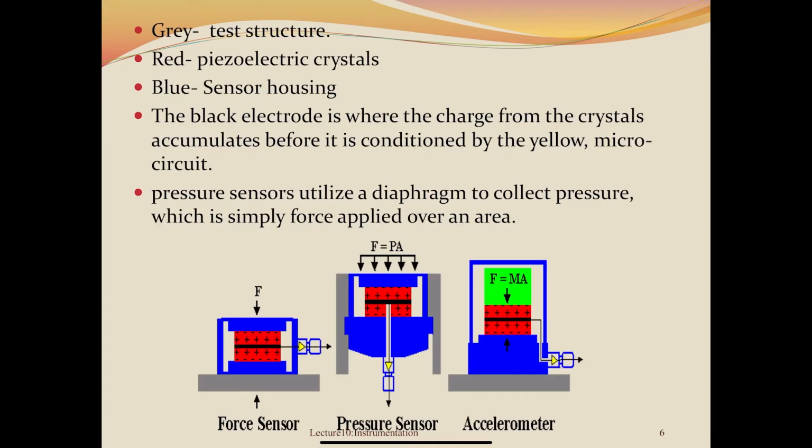These are examples of sensors that use the concept of piezoelectricity. We can see here there is a force sensor, pressure sensor, and accelerometer. All these sensors use piezoelectric material as the working principle behind the sensor. You can see here the gray area is the test structure, the red is the piezoelectric crystal, and this blue part is the housing.